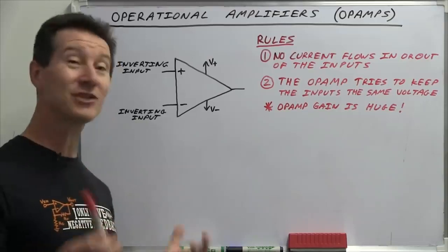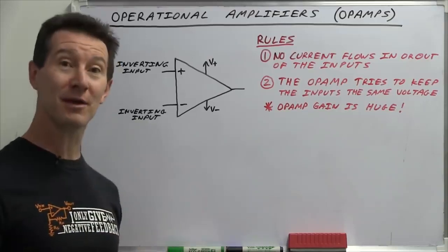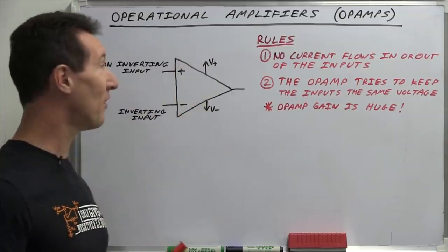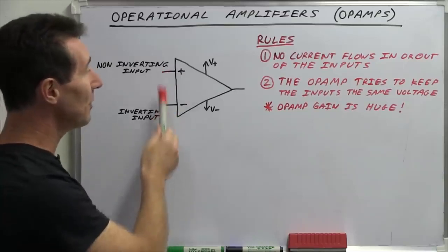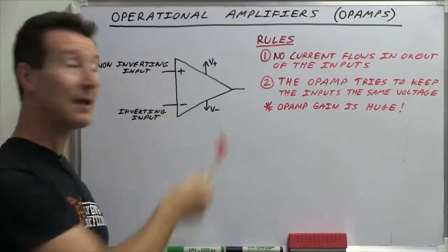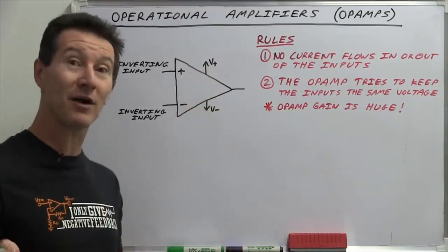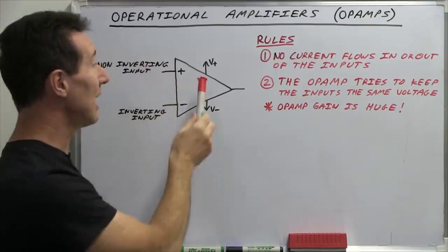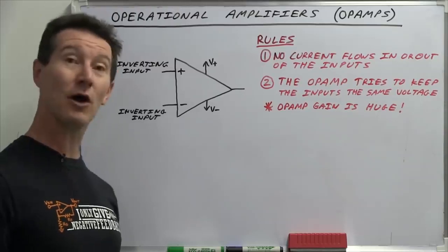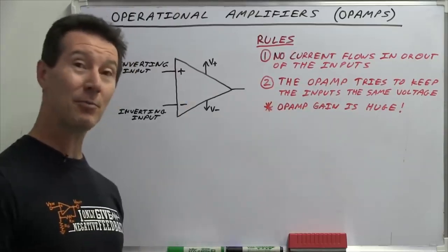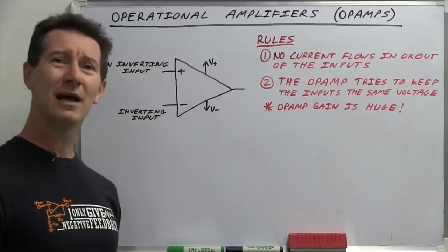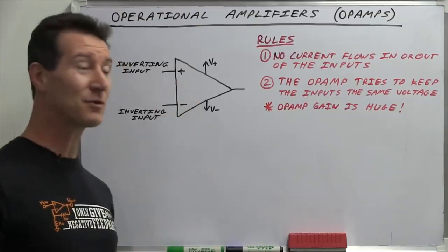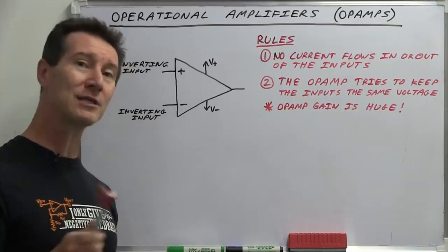So an op-amp is essentially just an amplifier. Yes, it can be used for those mathematical operations, but essentially what it comes down to is this is a differential amplifier. And what that means is that it's got two inputs over here, which we'll talk about, and an output, and it's got some gain in there because amplifiers have a gain. And what it does is it takes the difference between these two input signals, amplifies it by its internal gain, or what's called open loop gain, and gives you an output voltage. But op-amps really can't be used as differential amplifiers on their own, even though that's what they are. Rather confusing, but an important aspect you should understand.